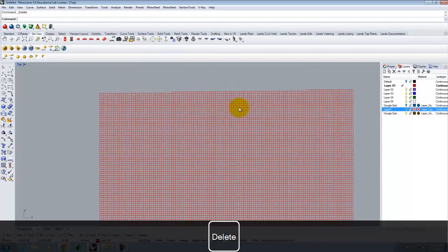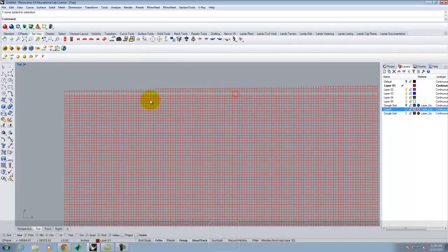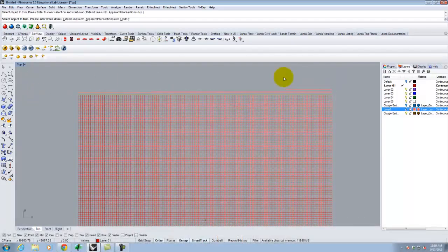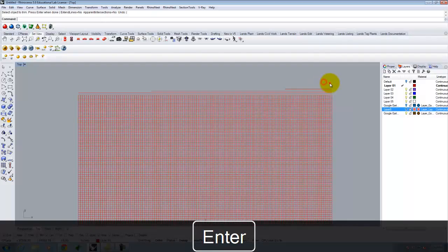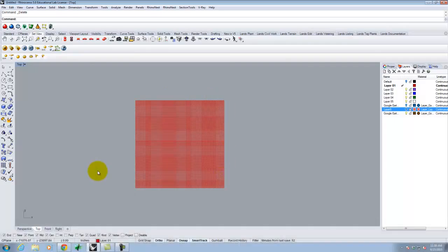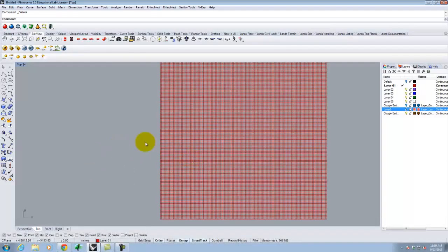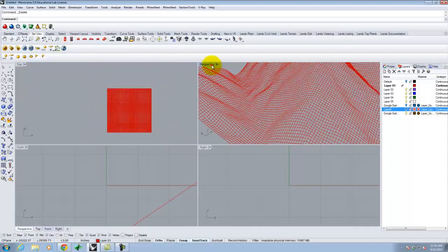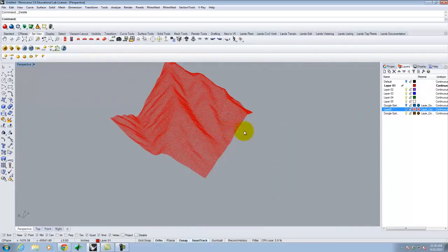Now I have to do the top still. So I'll type trim one more time. And we'll get rid of those. And so what happens is now I have basically a perfect square, or a perfect rectangle. I have a perfect grid, and now I can actually build a surface out of this curved network, or out of this network of curves, right?